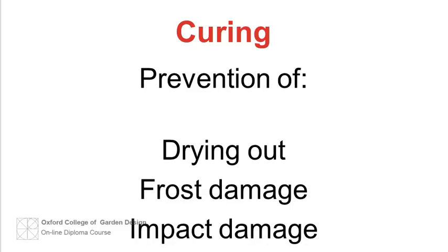In hot weather, concrete should be protected from too rapid drying out by the sun and wind, which will cause shrinkage cracks to develop. In cold weather, the danger is not only frost damage, but also a very slow gain in strength.